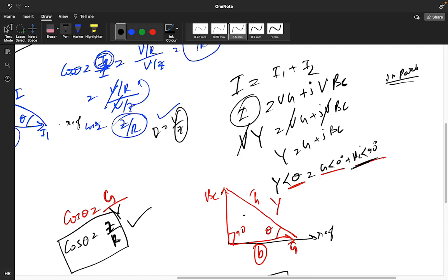See, the capacitor is leading by 90 degree. So for admittance, this part is leading. That's why we are saying, because we are getting a 90 degree lead for this susceptance. So the leading and lagging concept always comes with respect to a reference point. With respect to what we are saying.